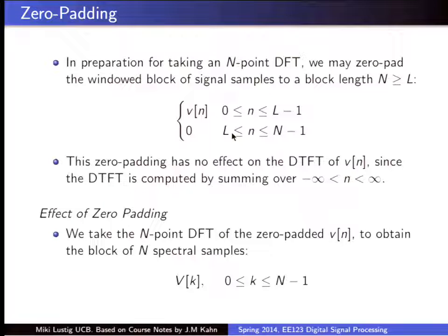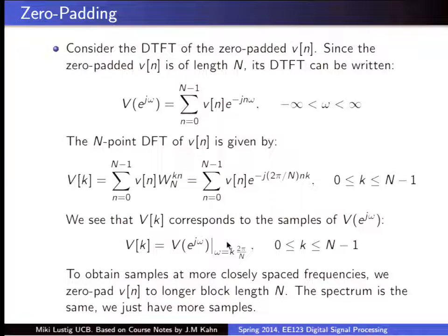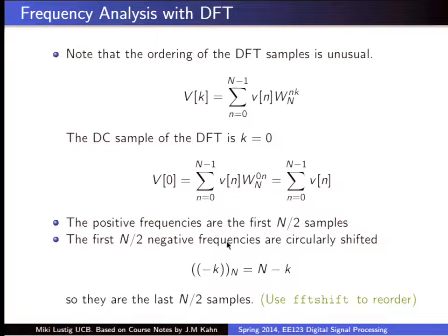So what does zero padding effectively do? You just get closer and closer to the DTFT. When you take the DFT of an infinitely large window, it effectively becomes the DTFT. Okay? So if I make it twice as long, I get a finer and finer estimation of the DTFT, and we showed it to you in the DFT lectures. So the effect of zero padding is really just sampling the DTFT better. Okay, just sampling it better.